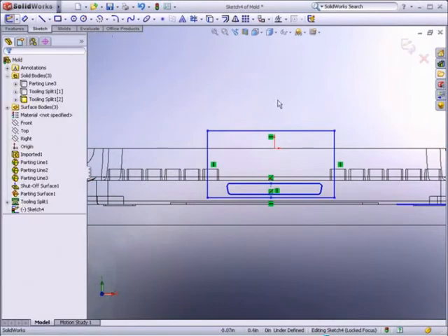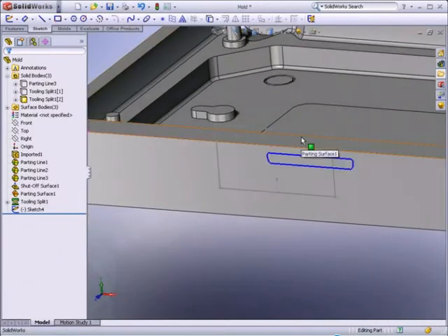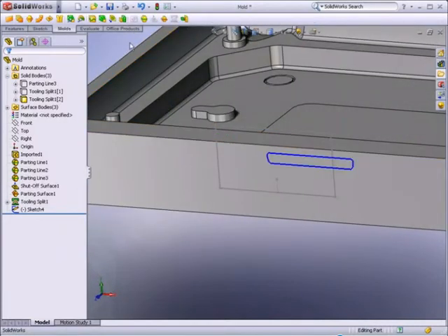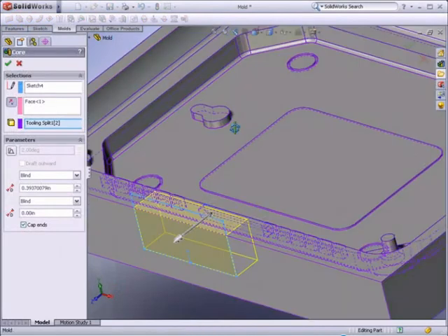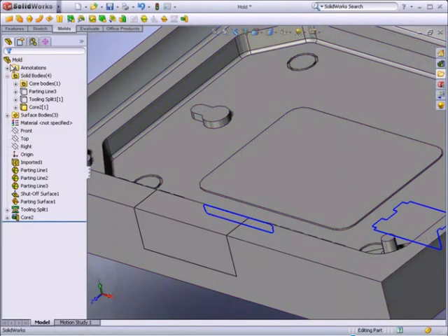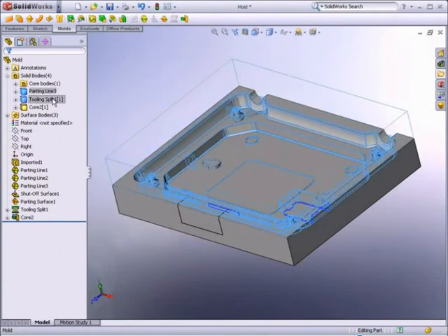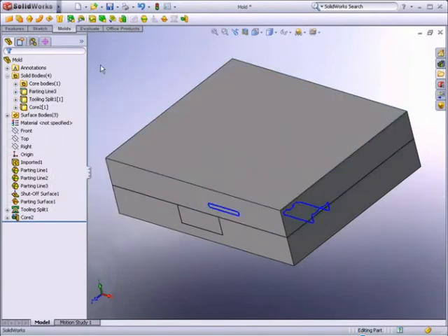Using the side core tool, simply drag and drop. The preview in the graphics area provides feedback that specifies exactly what size you need to make the side core. Now, we have quickly created the 3 pieces of core geometry required to generate the injection tooling. Since the tool has been segmented into 3 pieces, core, cavity, and slider, we need to turn those pieces into actual parts.